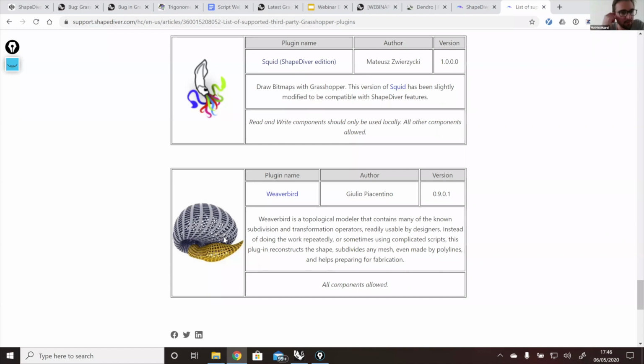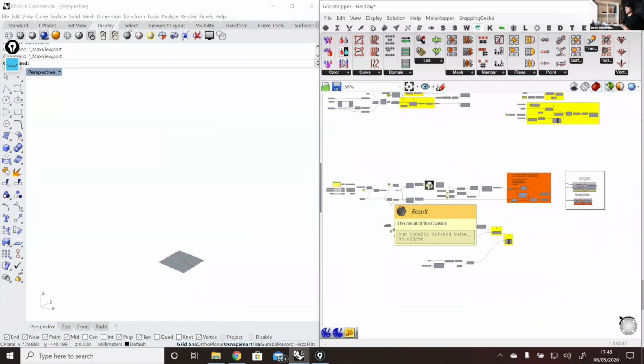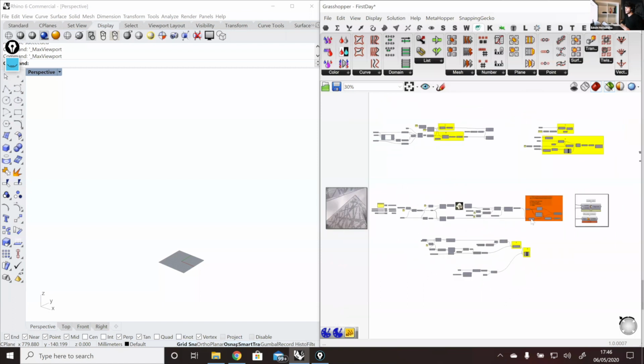I'm curious about some smaller optimization things, like using polygon center instead of area for centroids, or casting text in panels to floats. Do you try to get everything the most optimized, or only focus on the big issues? You can go as far as you want. Here we're working with a very simple script, but when your scripts get bigger and bigger, each of these details will count toward the final computation time. So we do try to use best practices from the little detail to the biggest one, especially if we know the script will become a huge script. We have done very complex projects that are still very optimized, because we take all of these optimizations into account.